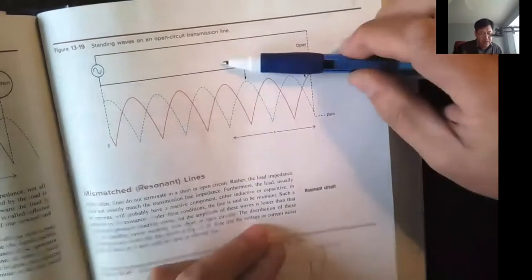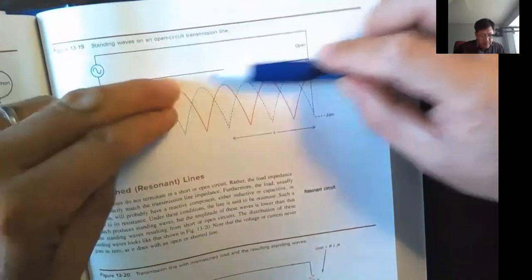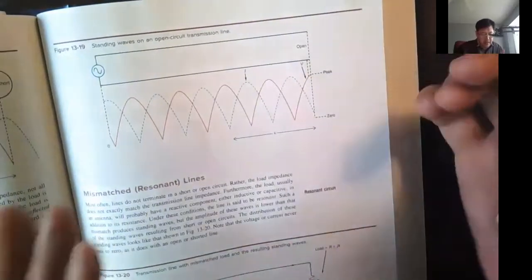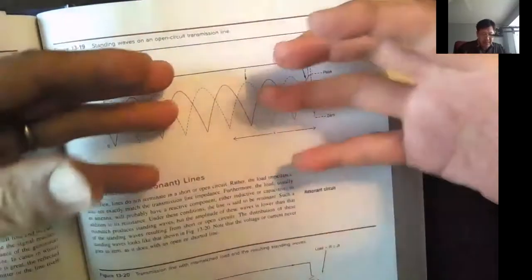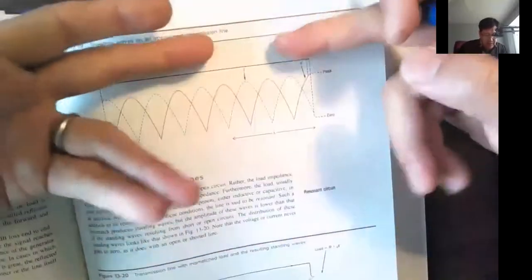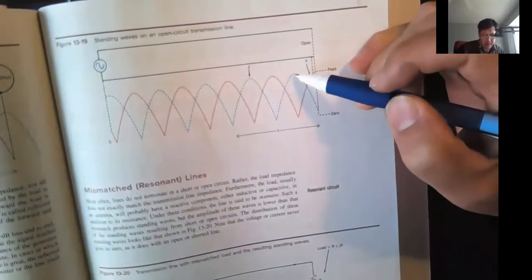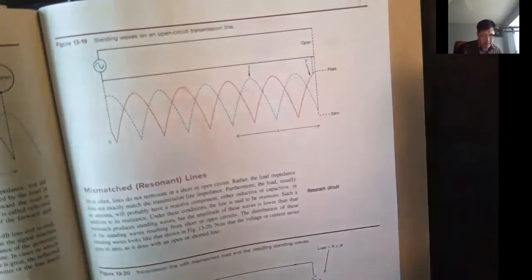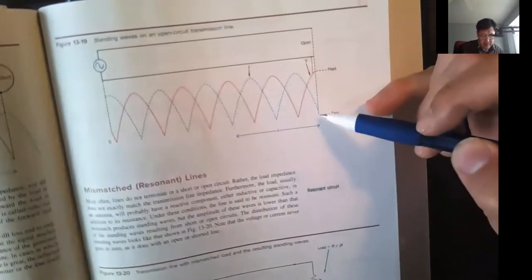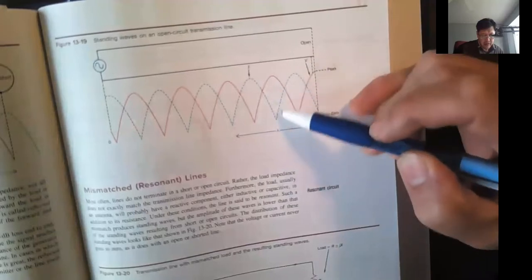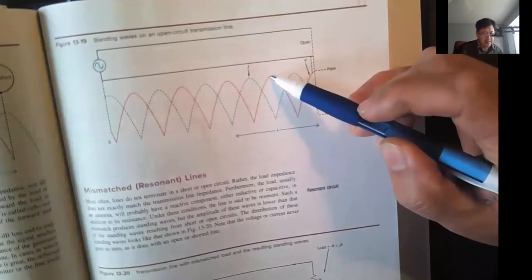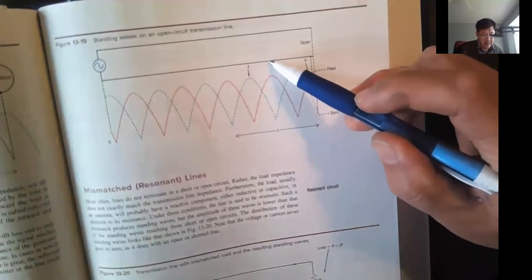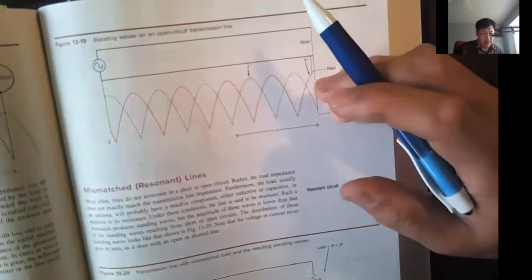Because the wavelength is so short, the current is literally just going on inside those wires. The electrons are compressed and expanded. If you think about it, on both wires, the density of electrons will be compressed and relaxed, compressed and relaxed. That's what's going on here. When we have the peak current right here, we have the maximum swing of the compression of the electrons and the release of the electrons. And then we have the minimum swing of current right here. Current will be 0. Of course, when the current is 0, we actually have the maximum potential swing. So that means at this location, the electrons are not moving because current is 0, but the potentials of those electrons are having a big swing.